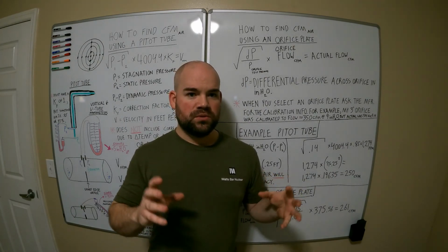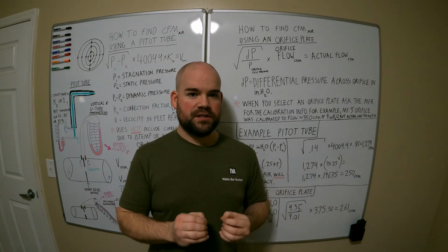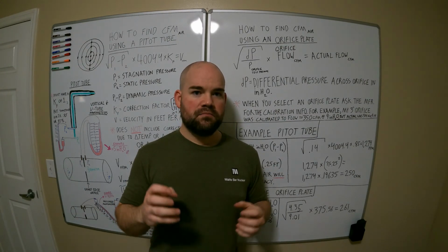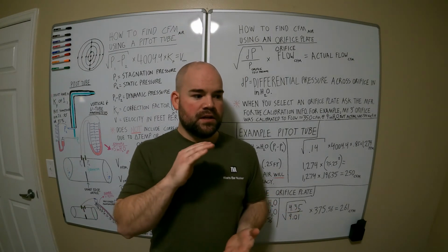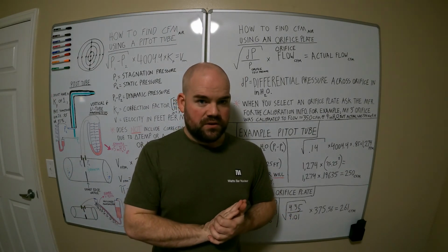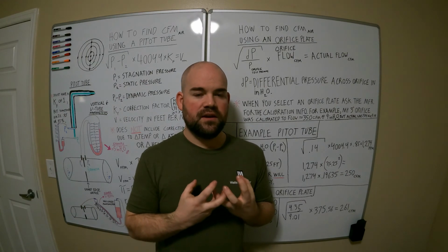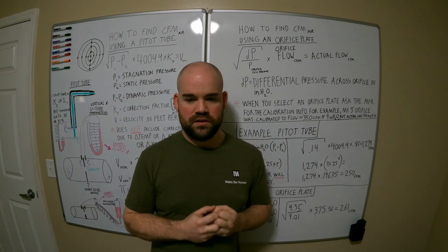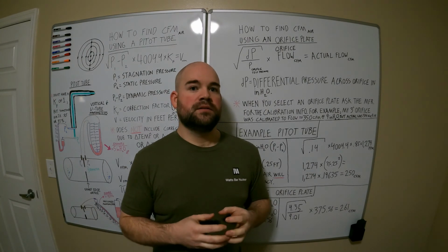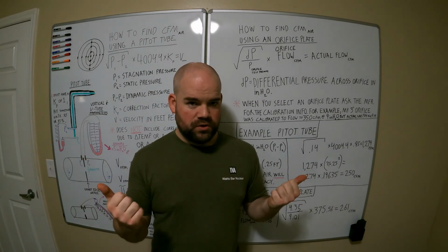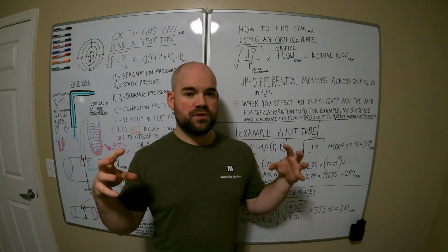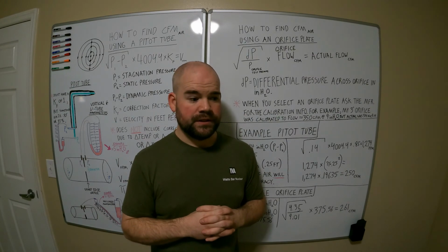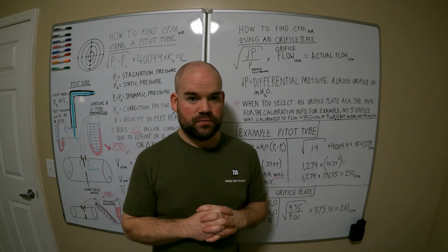The boost is only going to increase the amount of oxygen content, and it's directly proportional to the temperature, okay? Mass airflow, that's why you have mass airflow meters. The mass, the density of the air is what's important, and that's what makes power, okay? Temperature moves molecules further apart. Colder temperatures move those molecules closer together. So that's why turbos are better than roots superchargers.